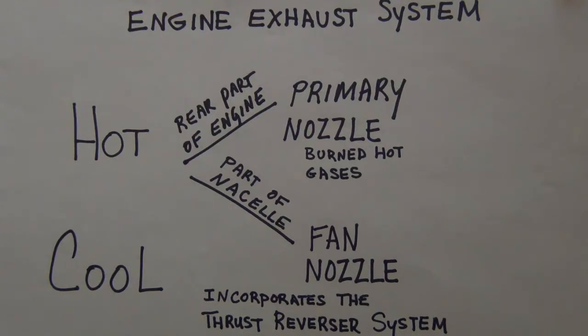One aspect I do want to mention before I talk about deactivation and lockout, because that has to do with maintenance if you're going to get ready to do that, is fire protection. There are thermal blankets that surround and are part of the thrust reverse system to segregate it from the rest of the aircraft, because it's a way to contain and protect the reverse thrust.